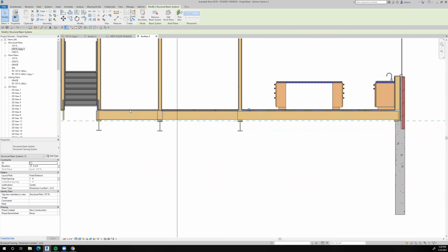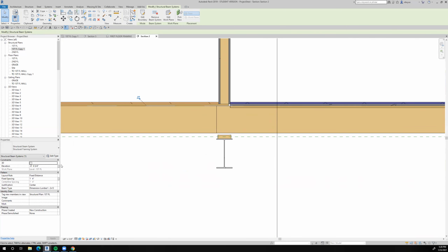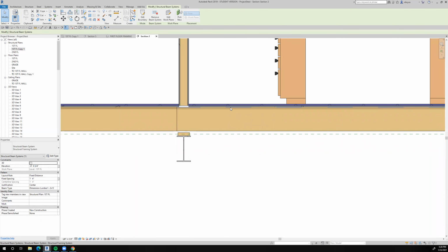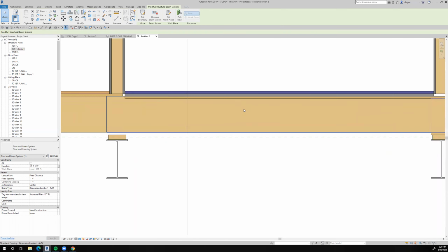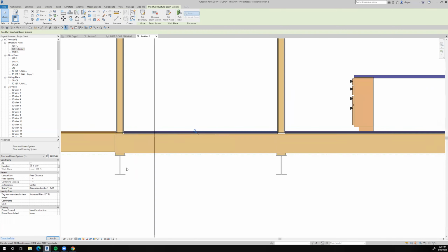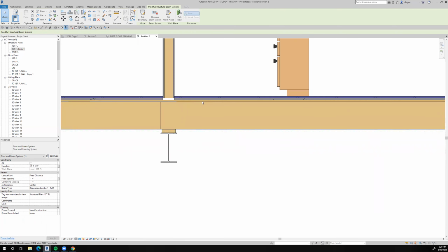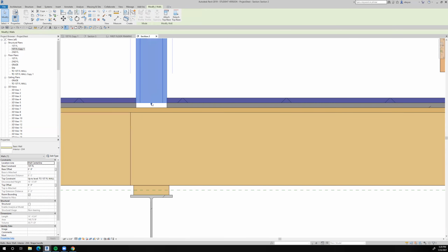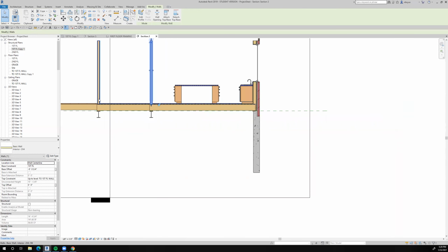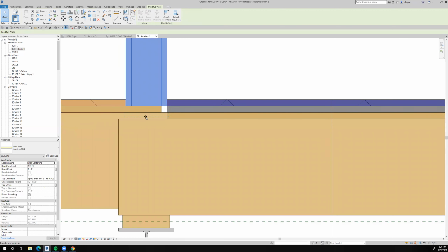What is this one? Let's look at this structural system. It's at -3/4 of an inch too, so this one needs to be -1.5 inches. And now look at that, it sits right. I'm looking for that dash line. I'm just hovering over here till I select that dash line. I can see that it's highlighted, and I will change that to minus 1.5 inches. And now that framing system is correct, because remember, we dropped that down so that we could get that extra 3/4 of an inch of what we call a mud base. And so in this case, the wall would actually go down because the wall gets framed before the mud base goes in.